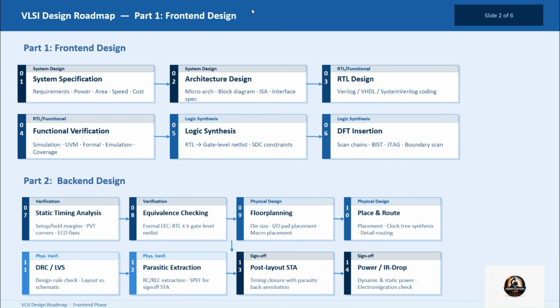These stages decide performance, scalability, parallelism, power efficiency, etc. The architecture engineer creates data path, FSM structure, pipeline stages, cache hierarchy, memory organization, protocols like AXI, APB interfaces. The important point is a bad architecture will be extremely difficult to fix later.